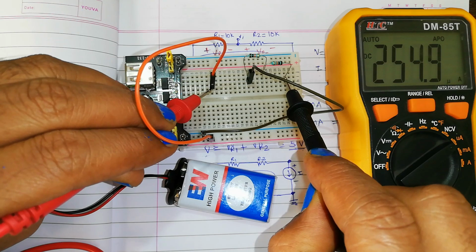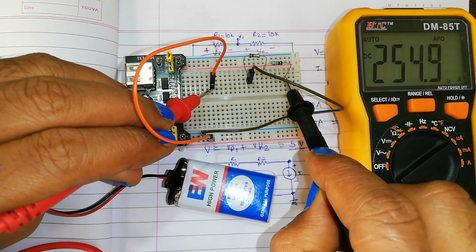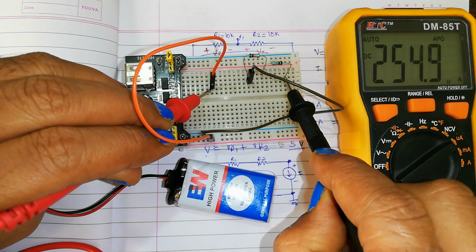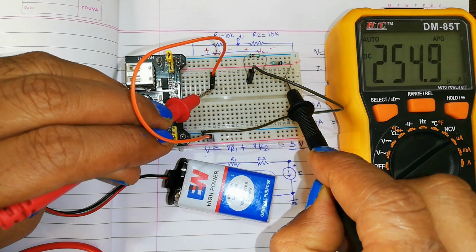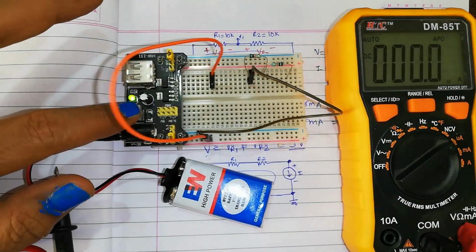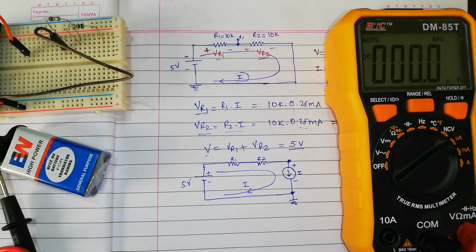So you see, this is how you measure various currents and voltages in the circuit. I have the positive probe to the positive terminal of the battery, and the negative probe of the meter to one end of the resistor. So that's it. We have conducted this experiment successfully, where I have shown you how to make a prototype series circuit using resistors, how to measure various voltages and the current, and how to learn about voltage division circuits.